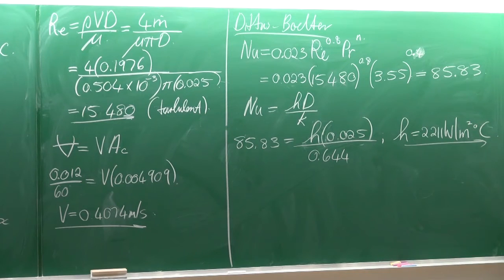Order of magnitude is about right for convection heat transfer. Natural convection heat transfer coefficients are in the order of 1 to 10. Heat transfer coefficients of fluids and gases through tubes are in the order of hundreds to thousands. For boiling, condensation, and two-phase flow, heat transfer coefficients are in the order of tens of thousands. So that's about right.